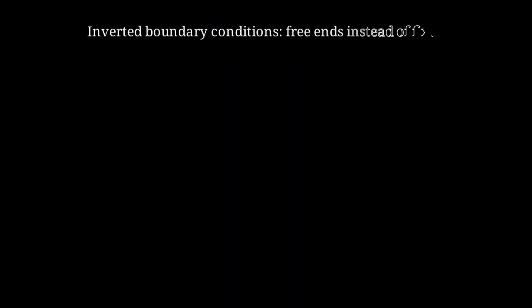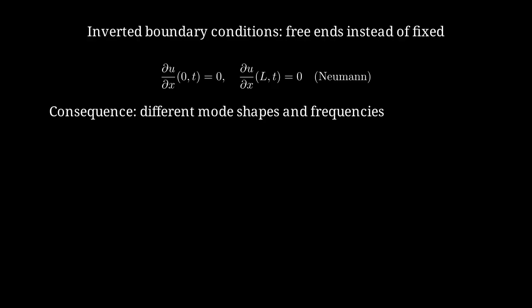What if we invert to free ends instead of fixed ends? This changes to Neumann boundary conditions. Neumann conditions specify that the derivative of u with respect to x equals 0 at both boundaries. The consequence is completely different mode shapes and resonant frequencies for the system.